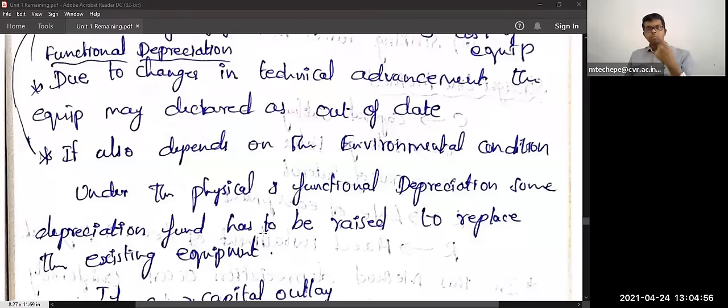In some cold countries, there will be a strong breeze. Due to that breeze, the transmission lines on the towers might be swinging and may easily touch the nearby transmission line, so that a short circuit fault may occur.